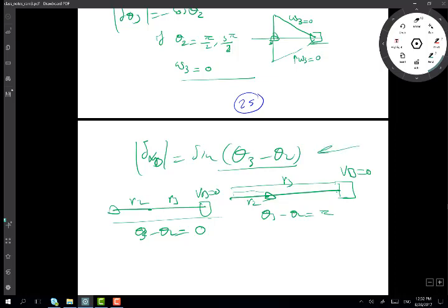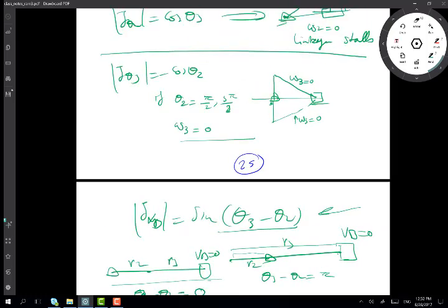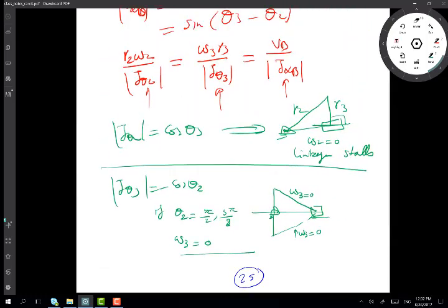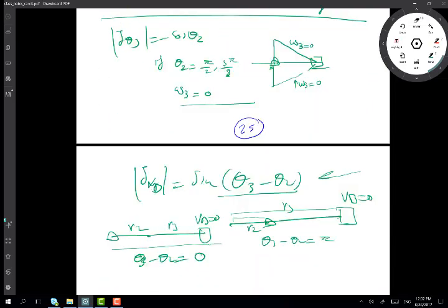I get this from the Jacobian, and they refer to this as mobility analysis. So we use this Jacobian representation to conduct some nice mobility analysis for the linkage. And if you go back here, if you want to calculate your omega 3 or VB, it's really simple substitution.